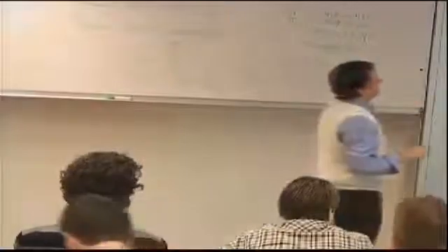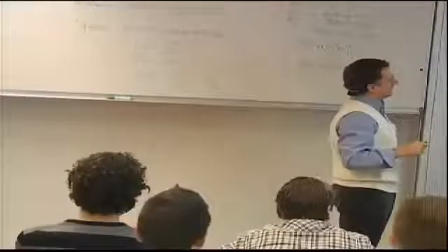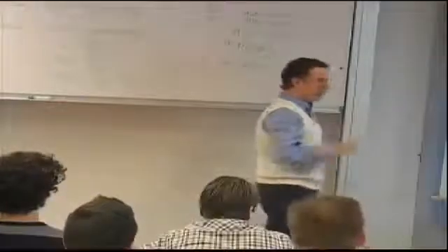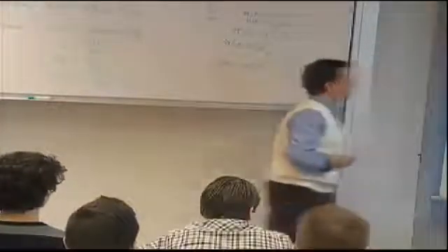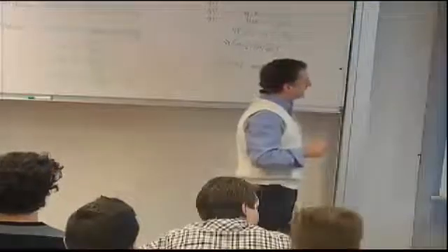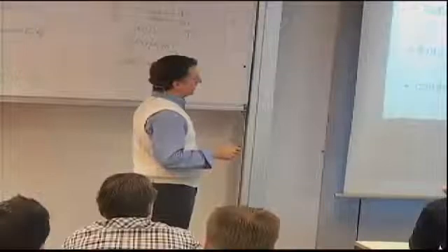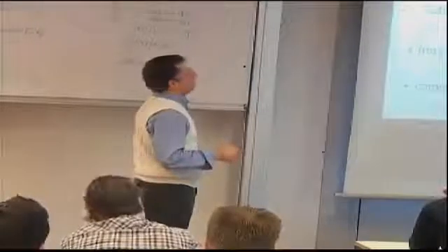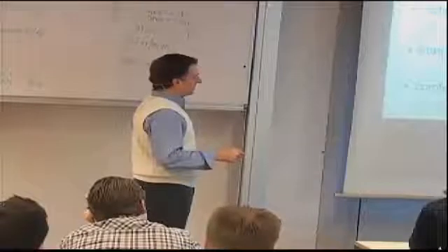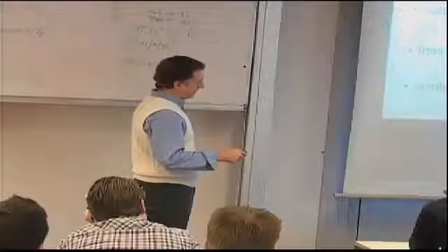I assume that the solution will be some function of x times cosine n pi y over b, for reasons that will become obvious in just a little bit. If I use this and I substitute in my governing equation shown here at the bottom, then the y dependence disappears because I have even derivatives of y, so the cosines reappear, and I'm left with a single equation on x, an ordinary differential equation, fourth order on x, which from standard differential equation theory, it's in terms of exponentials with the exponents.